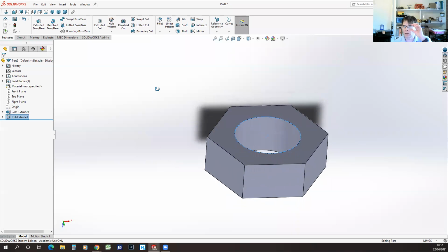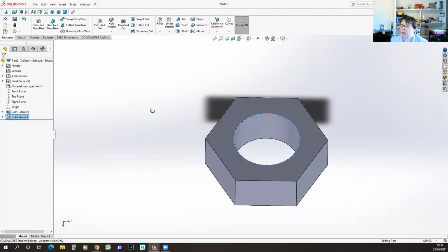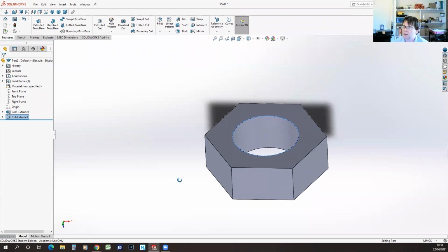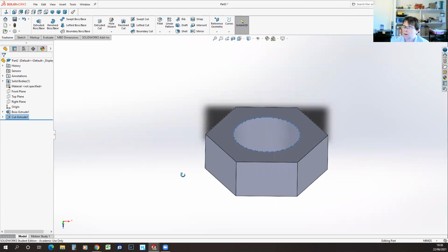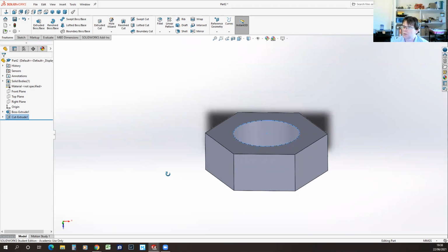And often when I'm doing CAD modeling for nuts and bolts and things, I don't go a lot further than that because it's just representative of the thickness of the nut. You can keep your CAD models as simple as they need to be for the purpose you're going to put them to. But let's say we wanted to, in fact, the one other thing which is sometimes significant is the chamfer, and the easiest way, I think, to do that is to do a rotational sketch.